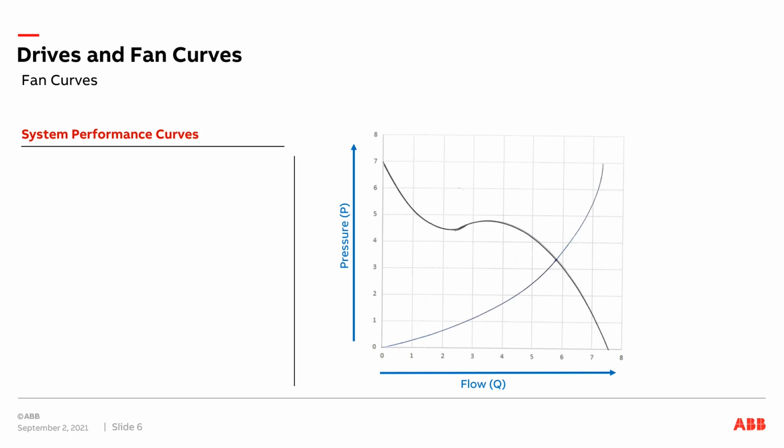Let's look at a system performance curve. When a manufacturer decides to test a fan, they hook it up on a test system, and the first thing they do is determine the maximum flow, and this is no system pressure. The fan's running through a set of ductwork, it's open-ended, and you get the maximum flow through the ductwork. For static, no flow, otherwise max pressure, they cap the end of the ductwork, and the fan is run up to full speed, and we find out how much pressure you can get, but there's no airflow.